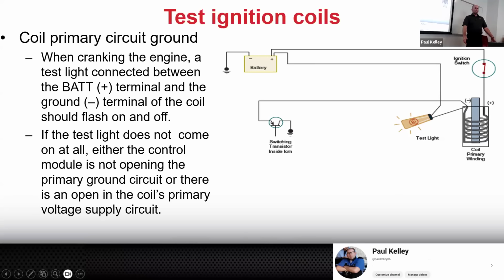You know what I saw? Nothing. There's no flashing, no nothing. And I was kind of like, all right. You know, because he was ready to go get a coil and the spark plugs and the wires and the fuel pump. And I was like, no, let's just do basic diagnosis. You give me 5 minutes and I'll tell you what I think, right? So look, it doesn't flash. If it doesn't flash, where do you think we would check next?